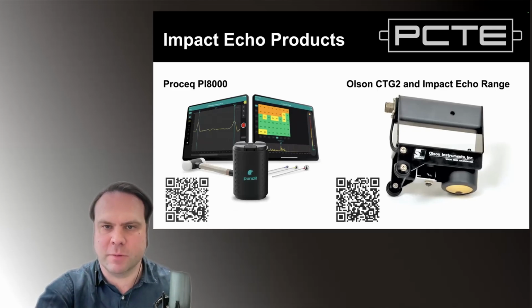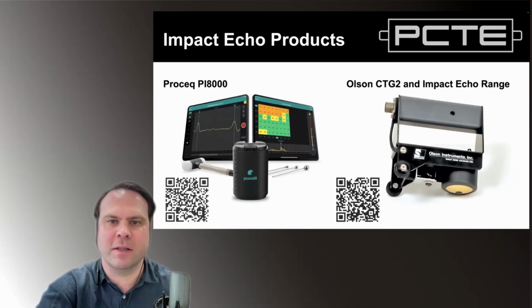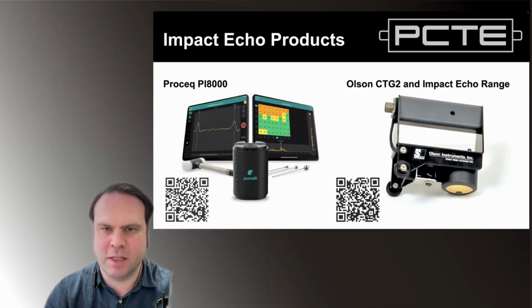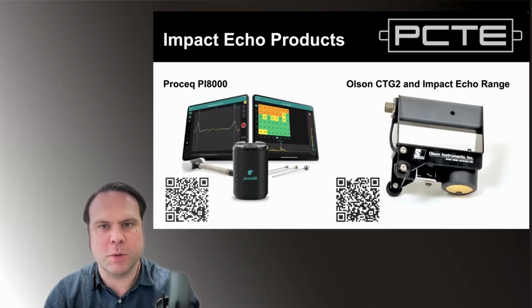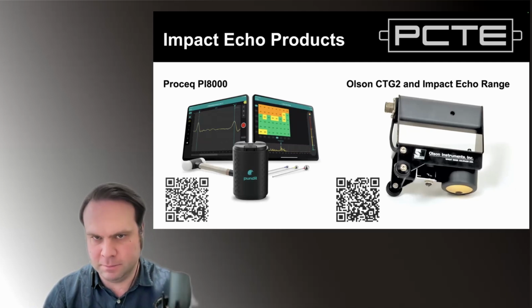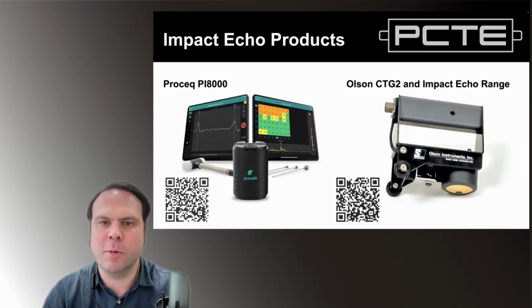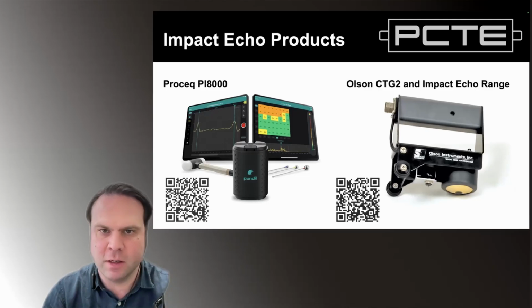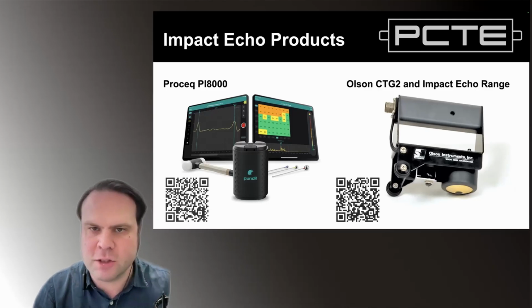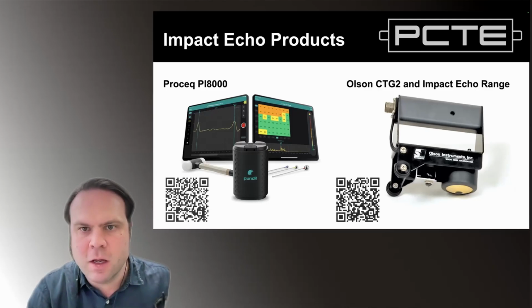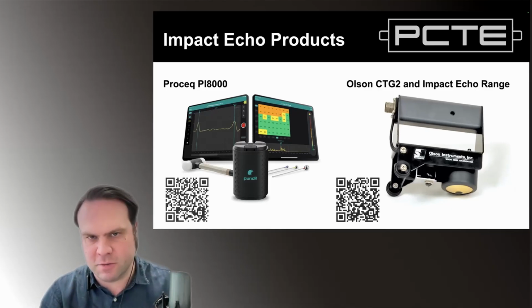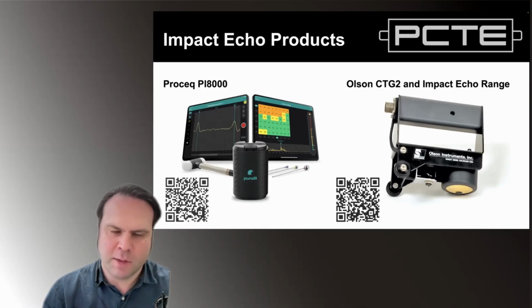Okay, so we have a question from Luke. What type of response would you expect to see from freeze-thaw affected concrete that contains small microcracks lowering the stiffness of the material? Would that be a low wave velocity, no response due to attenuation, or a reflection of the first shallow microcrack? Overall, do you think this is an appropriate test for freeze-thaw degradation in a 100 millimeter thick panel of originally 25 MPa concrete, on the theory of using a known thickness to find the inferred hardness?